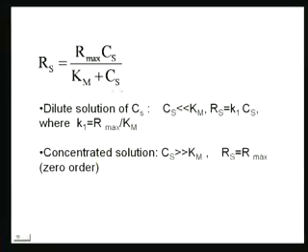That is what we are trying to do. Most of the problems that we are going to solve here, we are going to solve first using first order kinetics, and then using zeroth order kinetics, and we understand that our real kinetics and real solution lies between these two. So our actual solution will be bounded by the two solutions that we get. That's the strategy that we'll follow. Now if you want to do this on your own with the real kinetics, you simply have to solve this numerically.